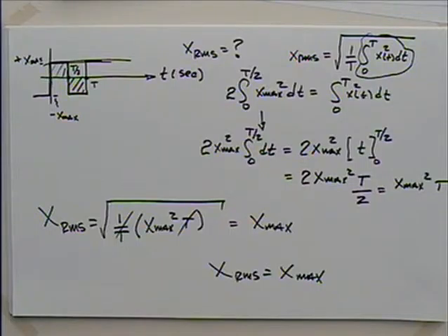Interestingly enough, if you get into welding technology in the last about 20 to 30 years, instead of using an AC signal, we've started with solid state and starting to use more square wave signals because we can get more power. We can put more power into the material with a square wave signal. So they'll look at people that use square wave power sources because they don't have any square root of 2 in here, right?